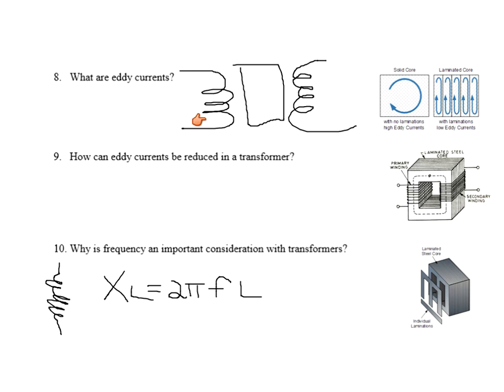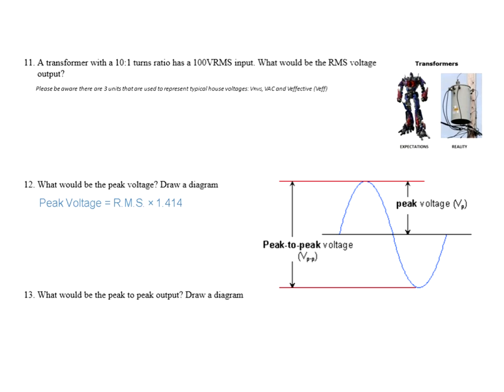If I take a high-frequency transformer and run it with a very, very low frequency, my number of ohms of inductive reactance would be very low. I might overheat from overcurrent. If I take a very low-frequency transformer, like one designed for 60 hertz, and try to use it at audio frequencies about 1K, the X sub L might be so high, no current will flow in it. So they are frequency sensitive because transformers are built with inductors for primaries and secondaries, and the number of ohms in the inductor, the AC ohms or reactance, is equal to 2 pi FL. They're designed to work around certain frequencies.